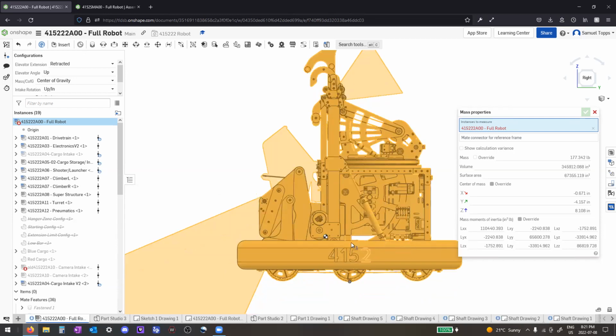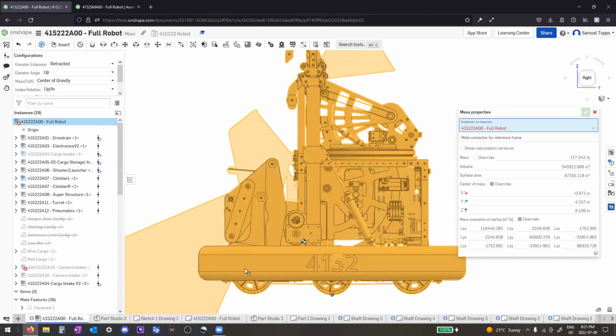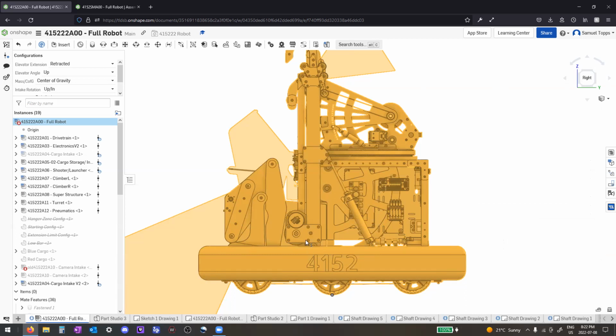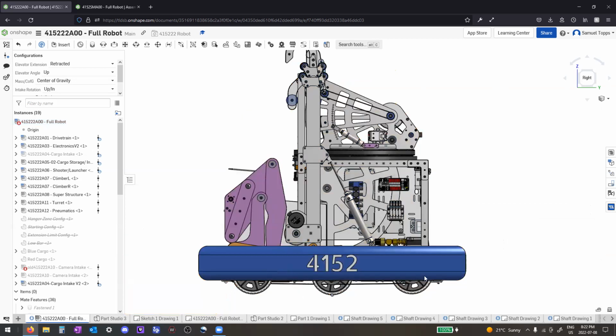The other thing to consider if your robot's going to be tippy is wheelbase. So some teams have been making smaller wheelbases this year, slightly more compact robots. But unfortunately, it means it's a little bit easier to tip because it's like a big lever arm, it's getting into torque calculations and stuff, but just a shorter wheelbase will generally be easier to tip, right?